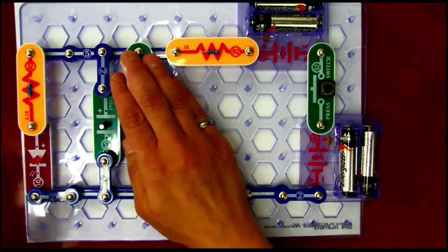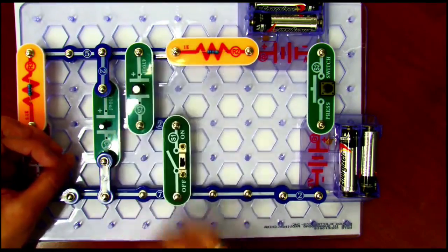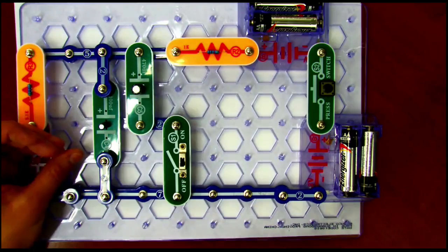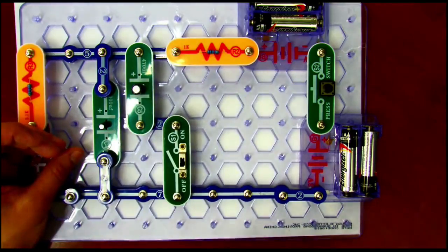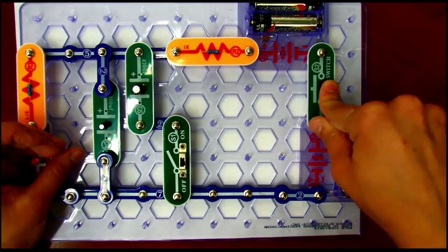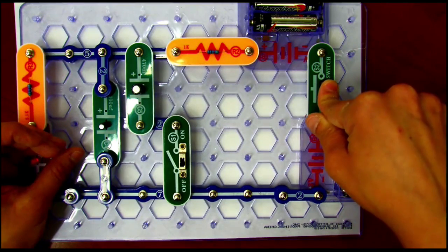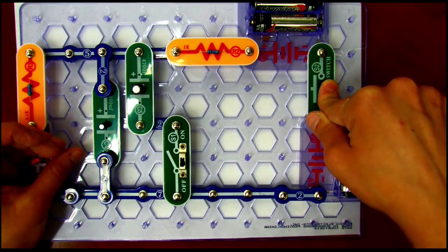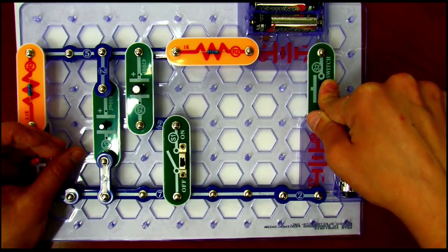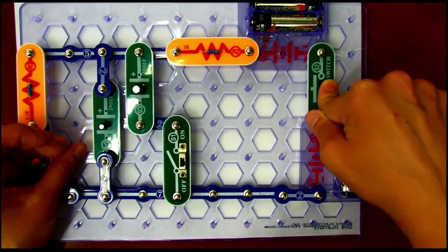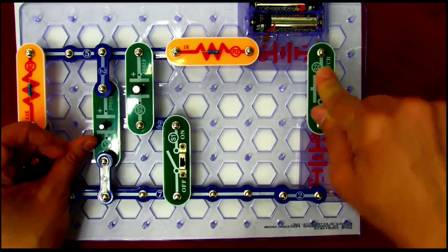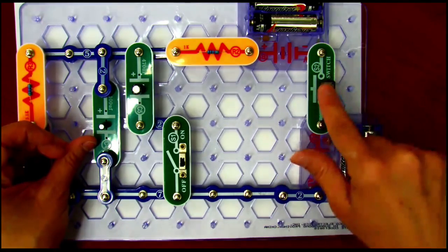The other one is off. It's out of the circuit right now. So we're going to block it off. I'm going to pretend it's not here because I need to put my hand around this light. So right now we're just going to use the 100 microfarad capacitor. I'm going to press the switch. It's powered. When I let go of the switch, you'll notice it does not instantaneously shut off, but the energy that I've stored in the capacitor is then used, and it slowly discharges, and you'll see the light slowly go off.